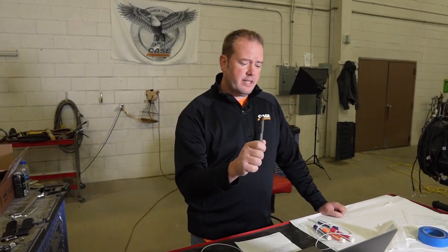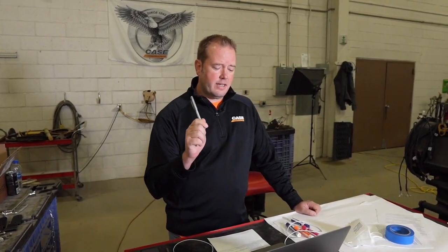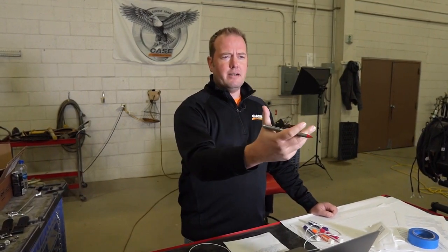And a second question that came in that ties to that, but from a different person, they have asked, I thought that idling for diesel engines was a good thing. What has changed? I think you touched on it a little bit in the initial discussion, but maybe hit that one again. Yeah, absolutely. Our emission systems today need high exhaust temperatures to be able to perform all of the chemical changes that happen in the exhaust. That higher exhaust gas temperature helps everything in that emission system in the way that it's designed to trap the particulate matter either better or handle it in a better way.